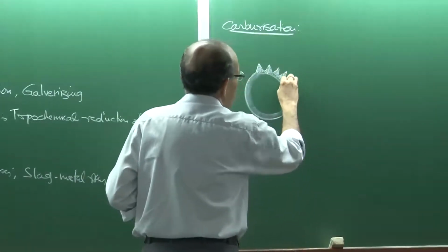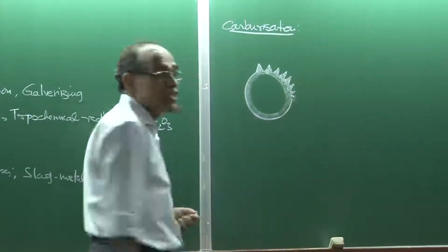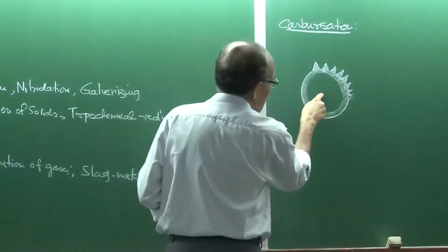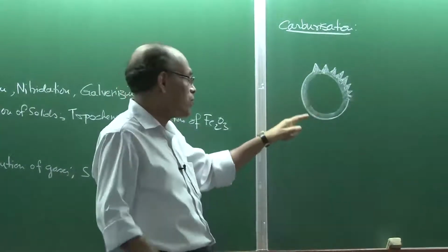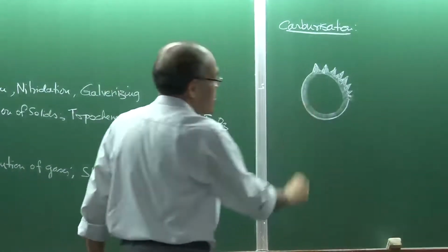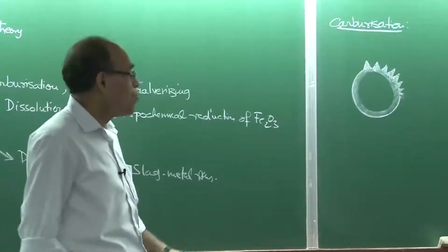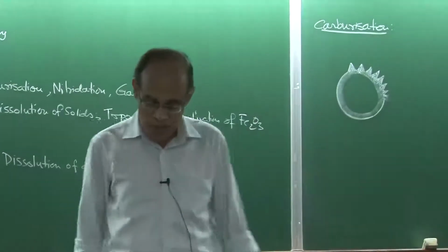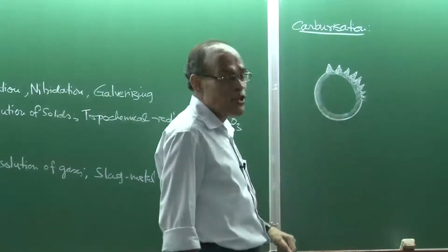And you all know that in steel, when high carbon is present, more cementite forms, and cementite is a hard phase. So therefore, we don't really want carbon to reach here, and so the bulk hardness is not so important. Bulk has to be soft, or relative to the surface, but the surface requires enhanced strength, and that's what basically is done when you heat a steel sample in a carbonaceous mixture, and then allow the carbon from the surrounding to diffuse into the solid.